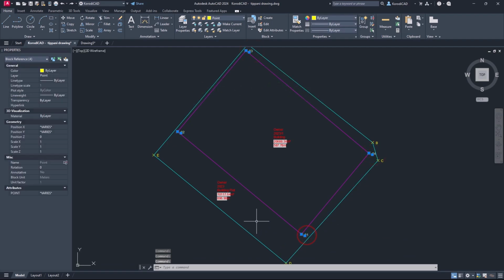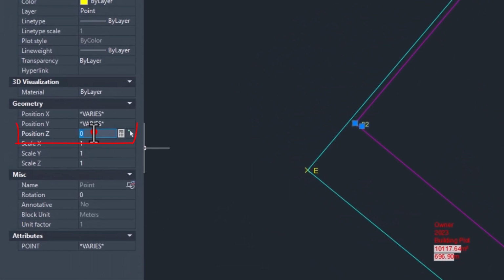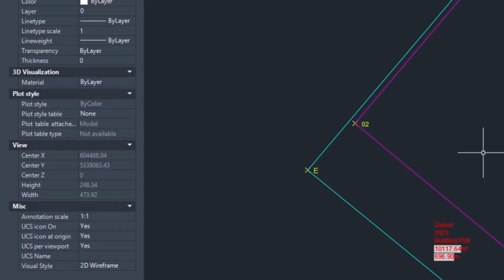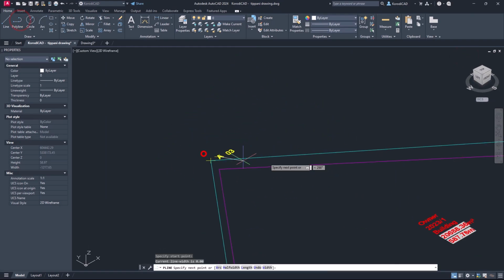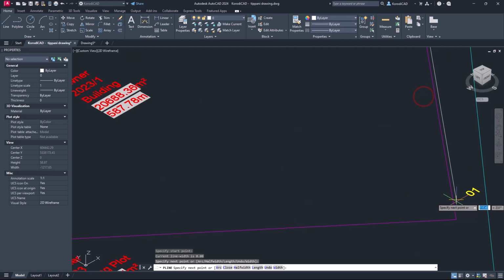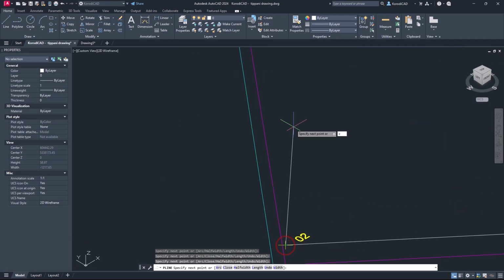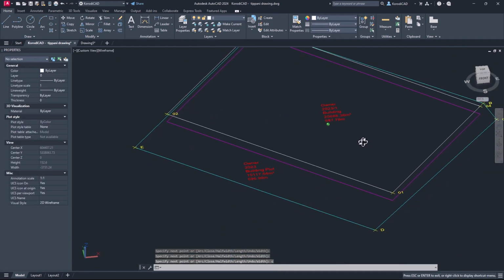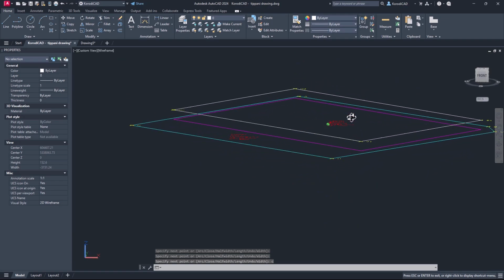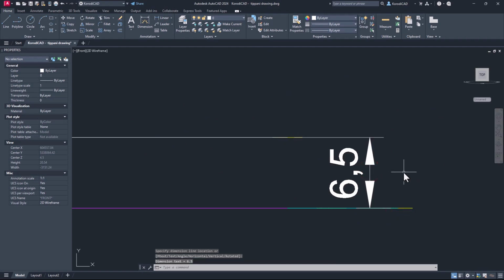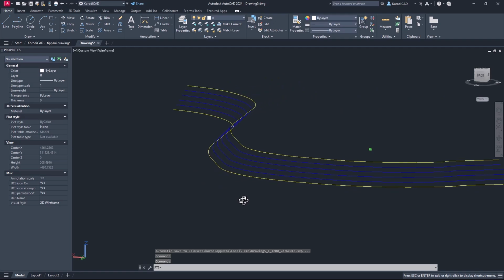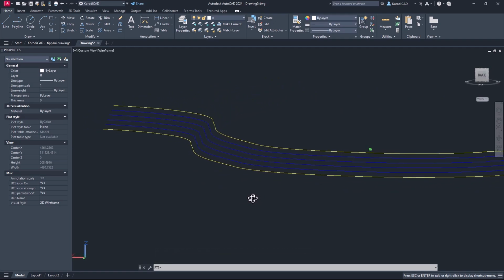Surveyors can also provide elevations, which can be plotted by entering the z-coordinate in AutoCAD. It is very important to pay attention to the reference point given by the surveyor according to local standards. Examples are ASL, above sea level, in Europe, and IVD, Indian vertical datum, in Asia, but countries and cities may also have their own datum 0. By connecting the resulting points, you can also draw contour lines.